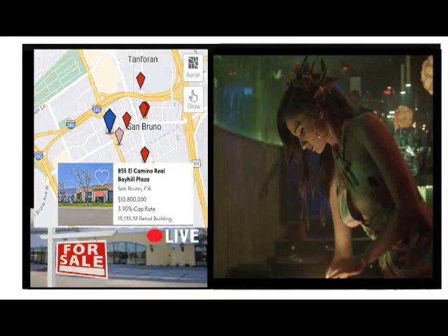Interior walls can be finished with plasterboard, also referred to as drywall or wallboard. Plasterboard is a preformed layer of plaster sandwiched between layers of paper and cut into sheets that are typically 4 feet by 8 feet. Its weight makes plasterboard difficult to handle, but it can be cut, if necessary, to fit around door and window openings, and it covers large areas quickly.